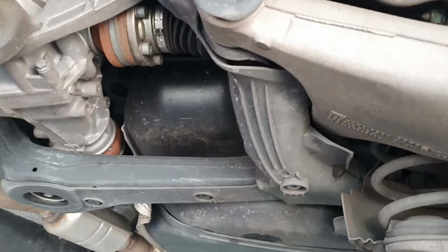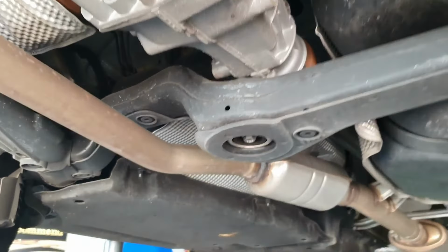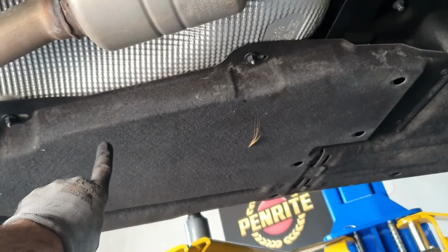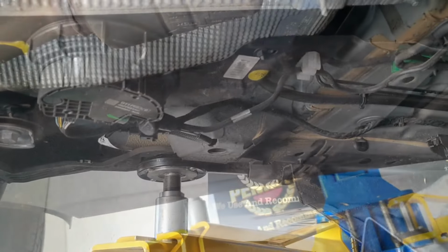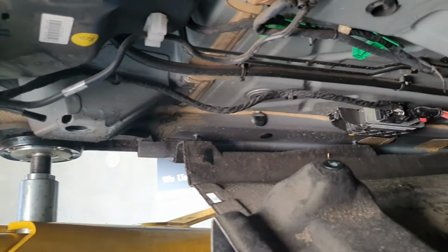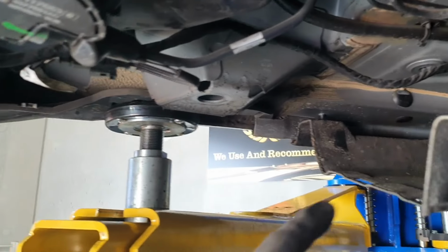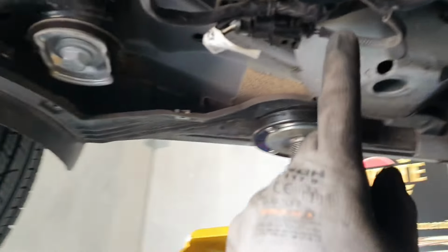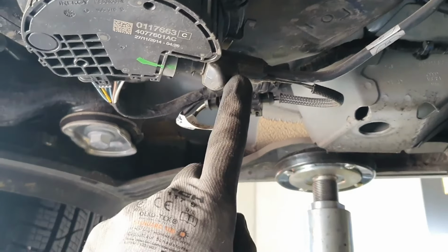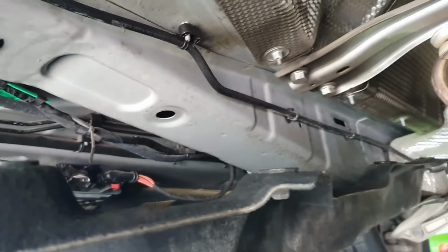Here we are under the car, guys. Got the main fuel tank over there. Our AdBlue system runs around this side, and our AdBlue tank is under this trim here. So we're going to pull these trims off and have another look. Alright, here we are with the covers off. As we can see, we've got our SCR module over there. That controls everything here with the AdBlue pump. The heater itself is actually built into the metering line that goes all the way to the front, directly to the injector on the SCR.